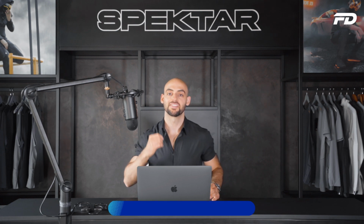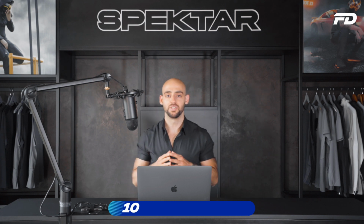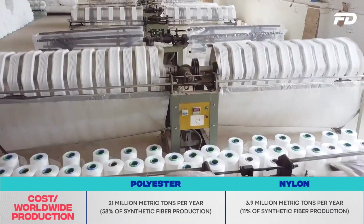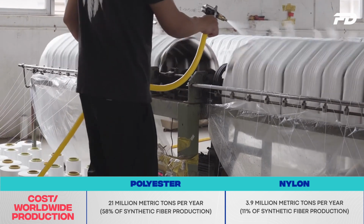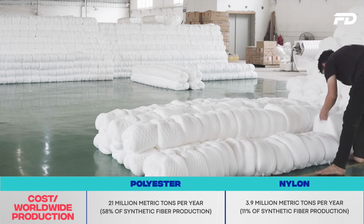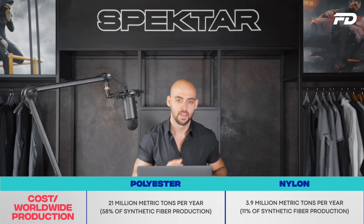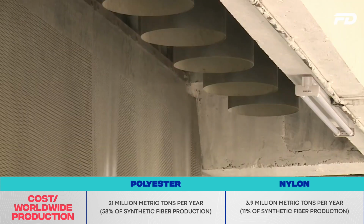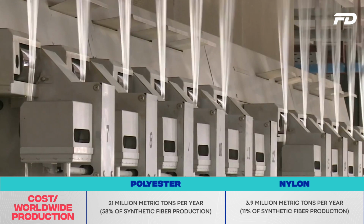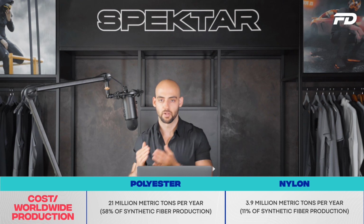Last but not least, we need to discuss the costs associated with both of these two types of fibers. And in terms of calculating the costs, we need to look at the worldwide availability. Statistics tell us that when it comes to nylon, we're producing around 3.9 million metric tons of the fiber per year, which amounts to around 11% of annual synthetic fiber production. On the flip side, when it comes to polyester, we're producing around 21 million metric tons. This here amounts to around 58% of total global production of synthetic fibers. So yes, polyester is going to be a lot more readily available, and per meter, it's going to be cheaper than nylon. So if you're on a budget, you're going to want to opt for polyester.